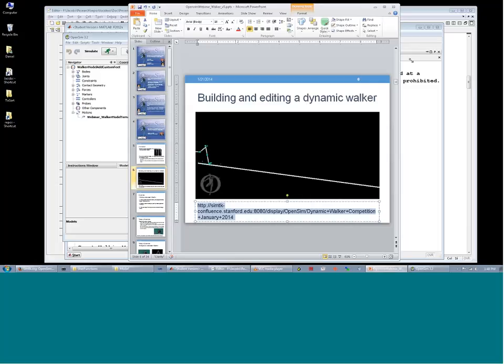There isn't a specific module for product design, but you can currently create a big set of bodies and controllers and actuators in OpenSim, similar to the process that you'll use for creating a dynamic walker. And that you can currently do by editing XML files or by using the OpenSim API in Matlab, like Dan talked about in the webinar, or in C++.